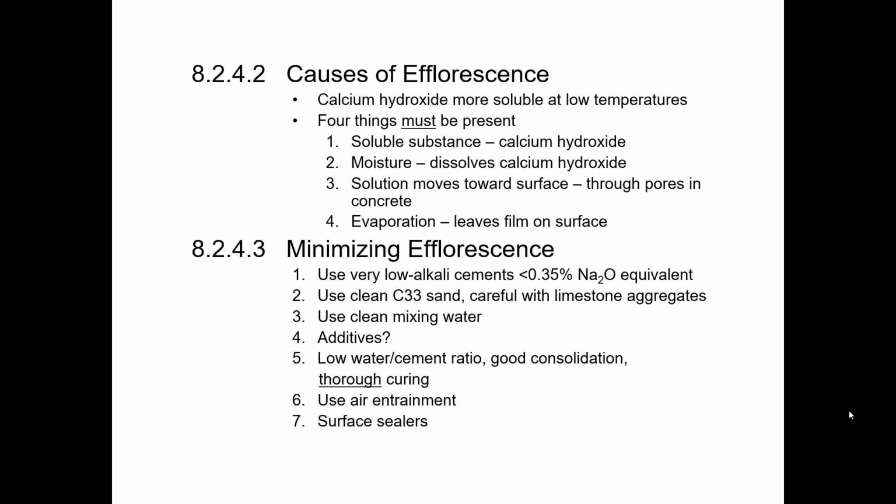That moisture has to be able to get into the panel and then move toward the surface and carry those calcium hydroxides with it. And then finally, that moisture has to be able to evaporate in order to leave those salts behind. If you can eliminate any one of those parts of the process, either in production or in service, then you'll eliminate this efflorescence altogether.